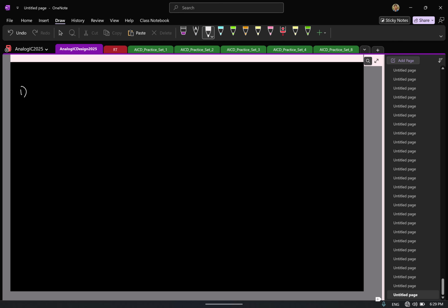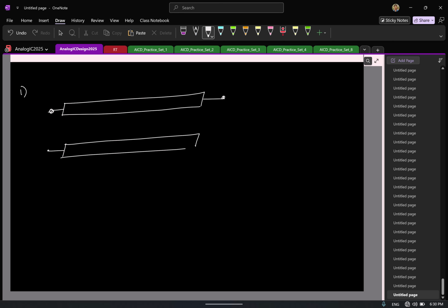Let us say you have a sensitive analog signal that you want to connect from, let us say, a sensor output or somewhere to another circuit. You basically connect it using a wire, which is a metal line like this. Now on the same chip, you might have, let's say, a clock signal getting routed from here to here. Let us say this is your signal V in, this is V clock. So V in is a sensitive signal, a very low amplitude signal.